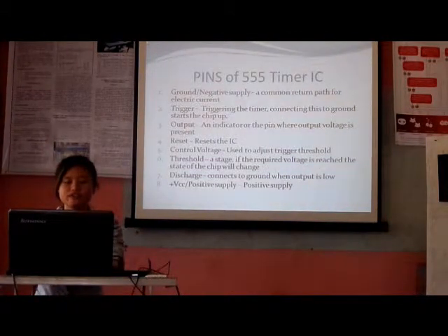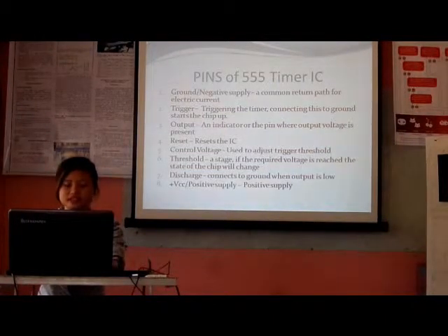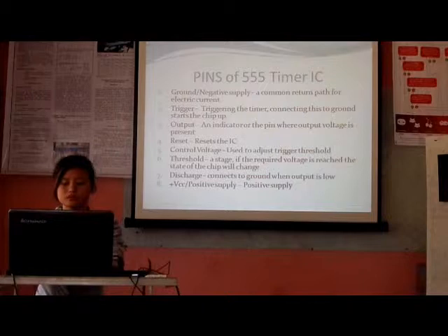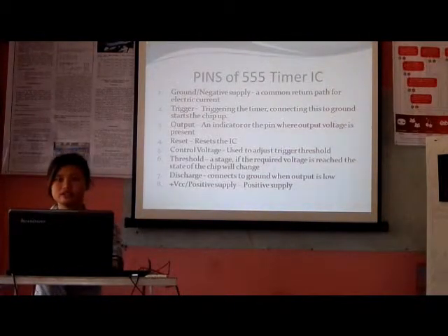Our pin number 4 of the 555 timer IC is reset. Reset is a timing interrupt. The timing may be reset by driving this pin to ground, but the timing does not begin until reset rises above approximately 0.7 volts. Approximately, it overrides trigger, which overrides threshold.